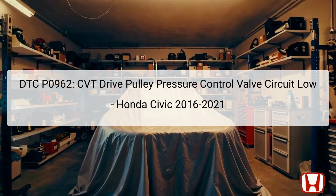If this regulation is disrupted, either through an open circuit or an intermittent connection, a DTC will be generated. The TCM monitors the current flowing through the solenoid and ensures it matches commanded values. If discrepancies are detected, it can lead to abnormal operations and ultimately trigger adverse driving symptoms.